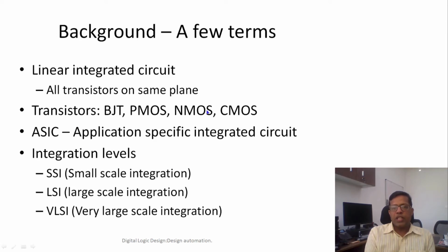You also see this word integrated here. Integrated means how many transistors are put onto one particular chip. That also defines the scale of integration. In small scale integration, SSI circuits, the number of transistors could be in the order of thousands and less than thousands, and in large scale integration, when the number of transistors grows beyond thousands, and when the number of transistors is in the range of hundreds of thousands, then it becomes VLSI, very large scale integration.